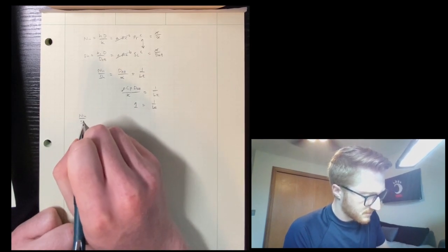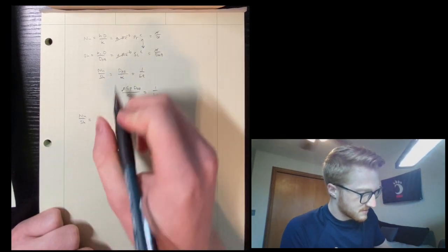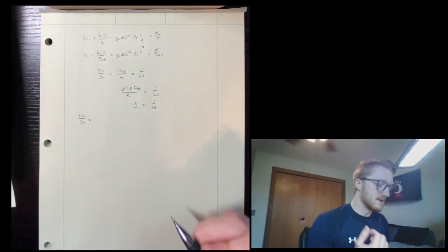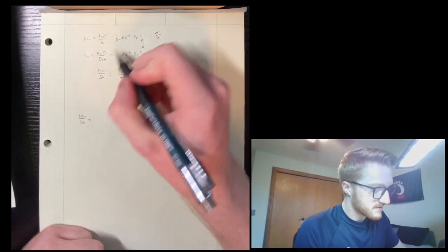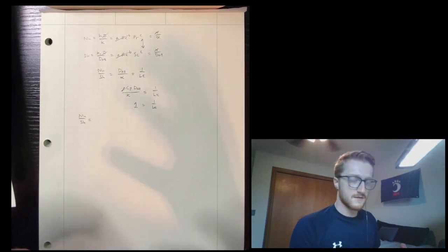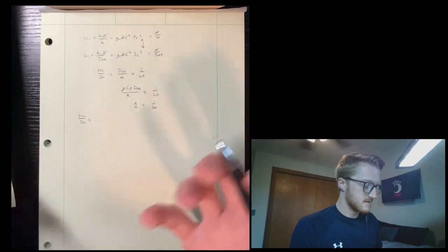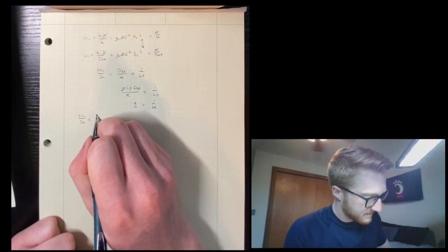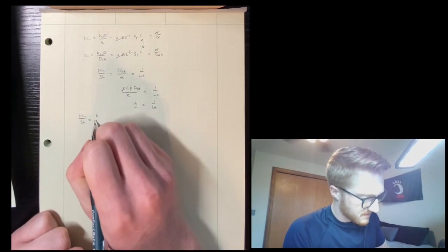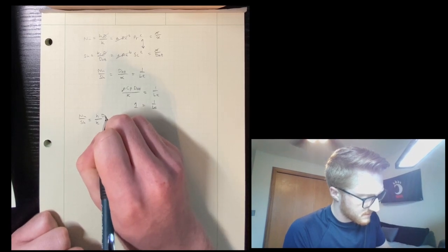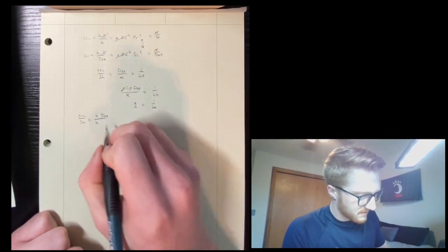The Nusselt number over the Sherwood number is equal to, and we're going to look more at this side of the equation now. And so again, we see that the characteristic length or the diameter, whatever the size of your experiment, is not going to matter. So that cancels out, and we're left with the heat transfer coefficient over the thermal conductivity times the diffusion coefficient over the mass transfer coefficient.